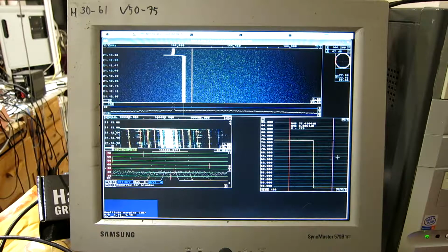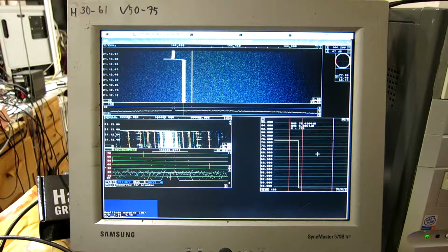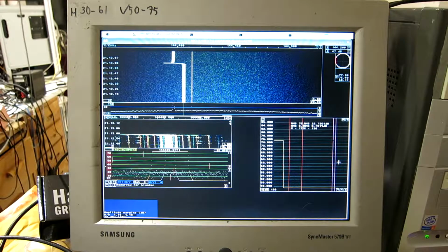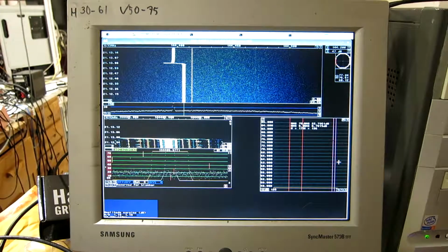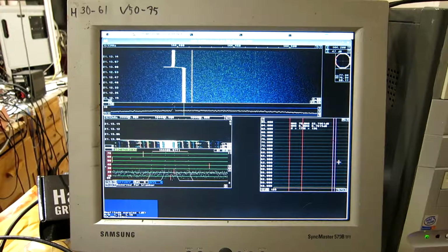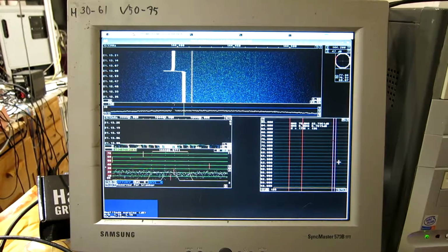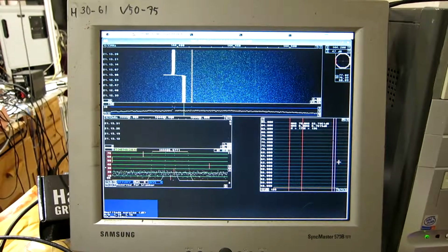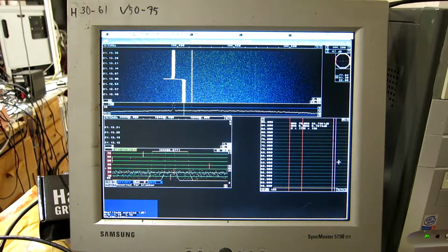And then I can read the noise floor here, 22.7. So this gives a dynamic range in the standard bandwidth of 500 Hz of 75.5 minus 22.7, which is 52.8. And the decimal doesn't mean anything, so I say 53 decibels.